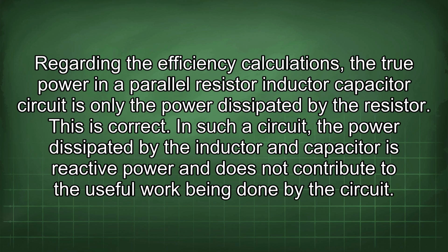Regarding the efficiency calculations, the true power in a parallel resistor inductor capacitor circuit is only the power dissipated by the resistor. This is correct. In such a circuit, the power dissipated by the inductor and capacitor is reactive power and does not contribute to the useful work being done by the circuit.